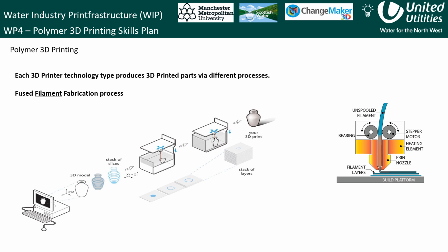The next step is to upload the 3D file into the 3D printer, either sent over a network or remotely via a USB drive. Once uploaded, the printing begins. It's important to observe the first few layers, as this is the time that printing incurs the most failures. The last step is to remove your print and post-process it to remove any support materials.